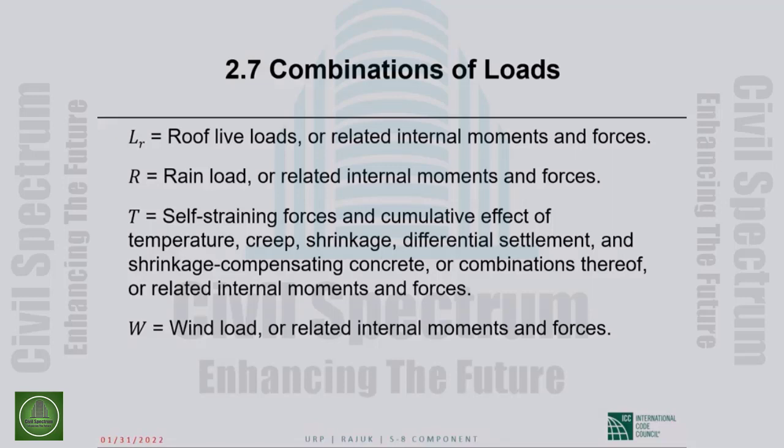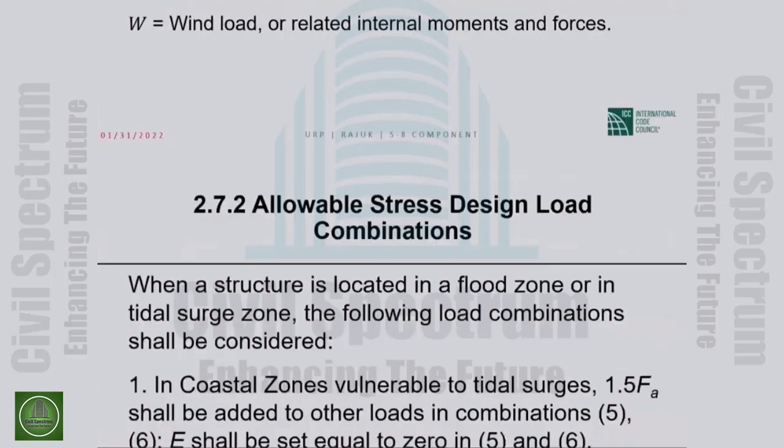When something wants to shorten and you don't allow it to shorten, you are in fact pulling on it. And that will set the concrete in tension. Concrete is weak in tension. So you are now looking at cracking. And unless you have provided adequate reinforcement, the cracking may cause very serious problems, including failure. Okay, so T, the effects of restrained shrinkage, restrained volume changes, have to be taken seriously. Okay, T. W is the effects of wind loads.